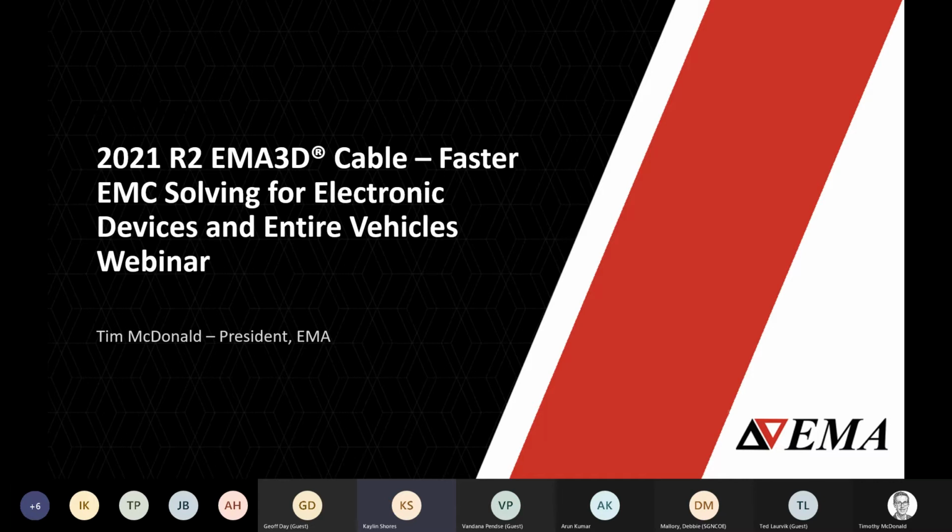He said, is Touchstone a separate application from EMA3D Cable? No, Touchstone is a file format for S parameter characterization. So it is a file format that EMA3D can export. Any IBIS or SPICE style, I say any, but the majority of commercially popular circuit modelers can import the Touchstone format, including ANSYS Electronics Desktop, but users may be familiar with other types of SPICE simulation tools that they're using and maybe have invested a lot in locally. All right, and then also, Ted, the slides will be available after the presentation is over.